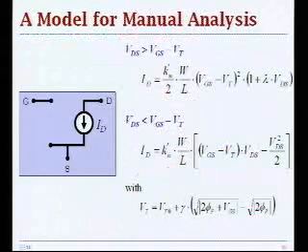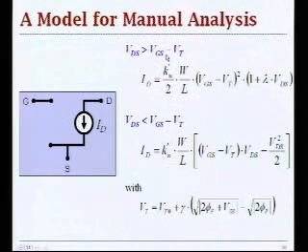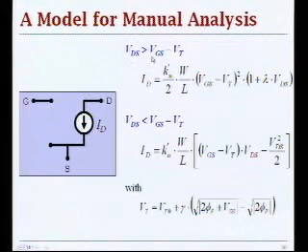So if you know all of this, then you can simply model. One of the ways you can model your transistor is through this model that represents a transistor as a current source. In the linear region, you have this expression over here, and in saturation, you have this quadratic dependence with channel length modulation, where you define your threshold as given in this equation. So you really need a couple of parameters from the technology.